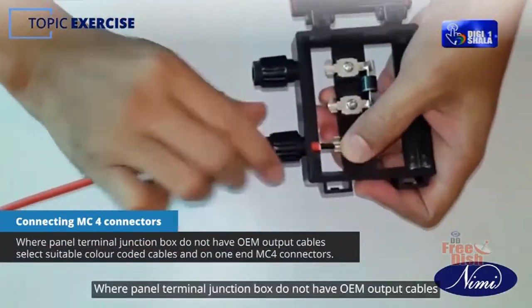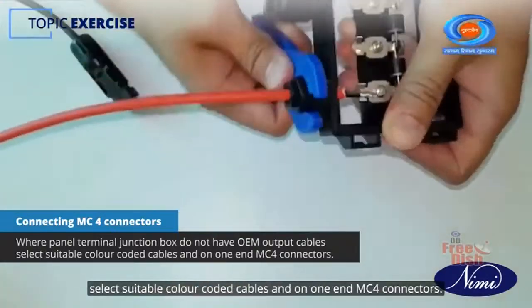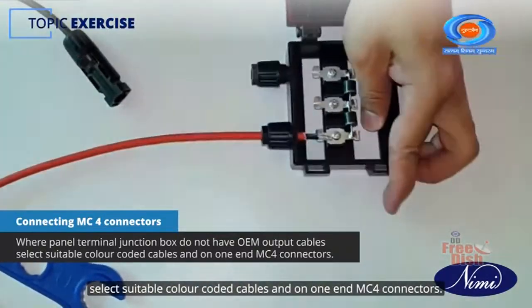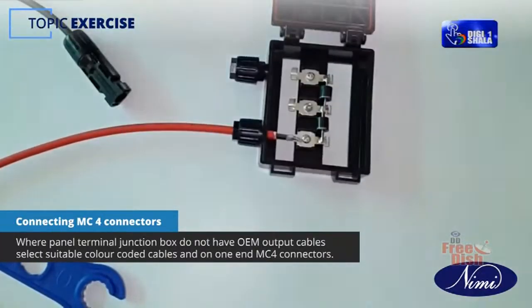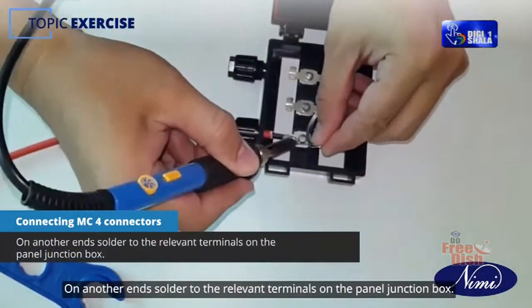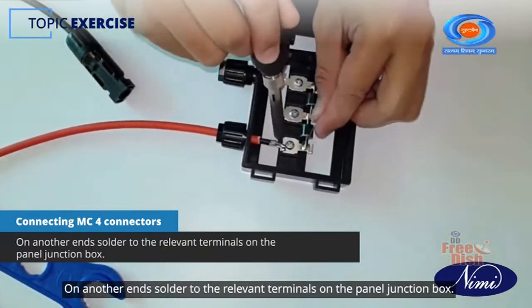Where panel terminal junction box does not have OEM output cables, select suitable color-coded cables and on one end fit MC4 connectors. On another end, solder to the relevant terminals on the panel junction box.